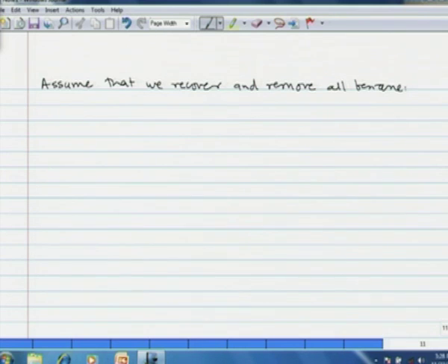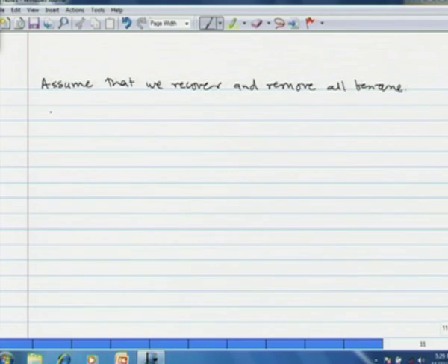Now, as I just mentioned, at steady state of the process, all of the fresh toluene should get converted, otherwise there will be an accumulation of toluene in the flow rate. Now, let us say that the desired production rate of benzene is Pb mole per hour.